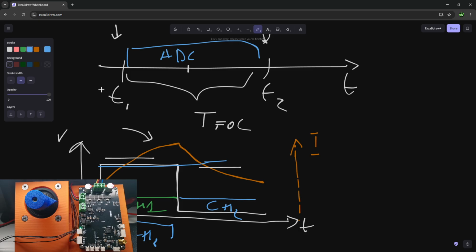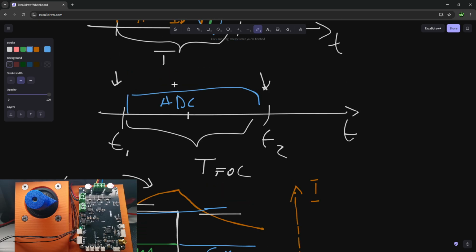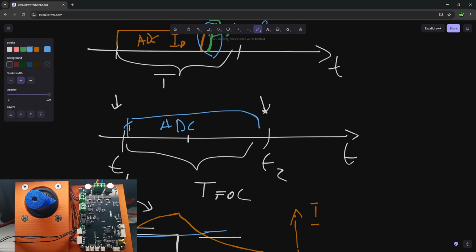And also why we need a separate ADC for other channels: if we want our whole period for current measurements, we don't have time to measure anything else, so we need a separate ADC that will measure temperature, voltage, temperature 2, whatever. Because our first ADC measures current on one phase and our second ADC measures current on the second phase. I hope it gets the point.